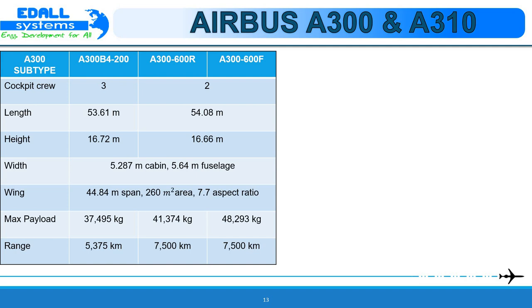The succeeding three-digit number represents the aircraft series, the engine manufacturer and the engine version number respectively. For example, in this A300-600R, the code is 6 for series 600 and 0 for engine manufacturer and the engine version 0. Thus, the aircraft number is A300-600. An additional letter is sometimes used. These include C for combi version, that is passenger and freighter, capital F for freighter model, capital R for long range model, M for military model and capital X for enhanced model.